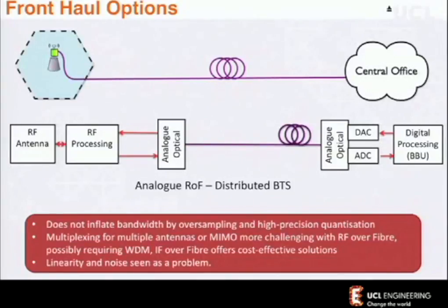So what's the advantage? Well, now I've not inflated my signal by digitizing it. One of the errors that I'm sure none of the MSc students here made is the idea that digital is narrow band. Well, no, as soon as you digitize anything, you blow the bandwidth up out of all proportion. You often get back again by some form of compression, which is easier in digital, but I saw at least that mistake once in the ITN exam this year.